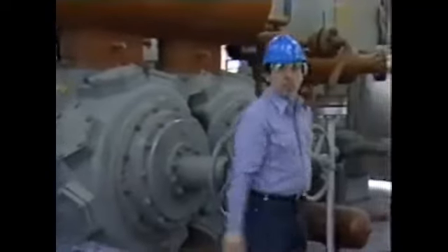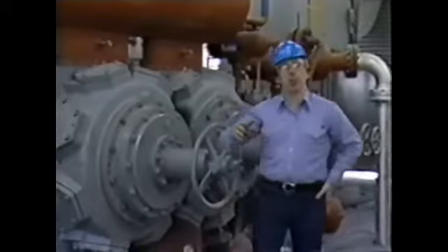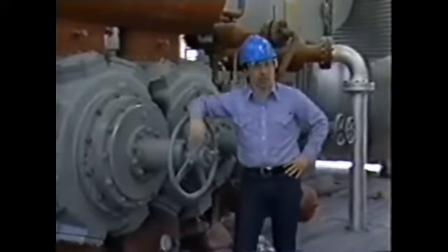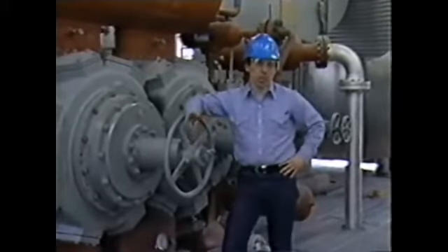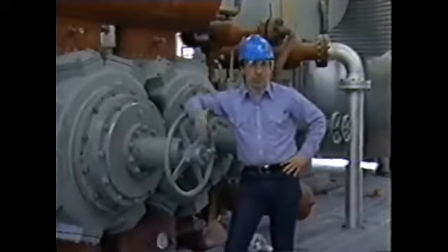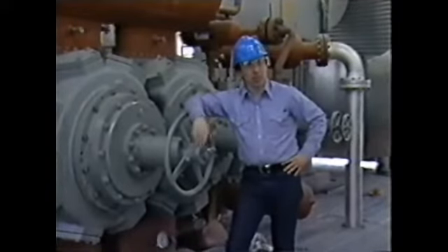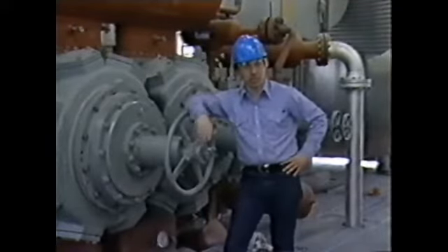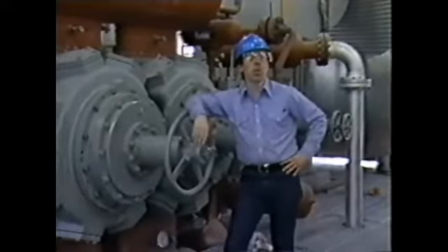In certain instances, gas must be compressed from a low pressure to a high pressure to meet sales requirements or field applications. This increased pressure is accomplished through stages of compression. But due to the amount of power required, it's not feasible to raise the pressure of the gas from low pressure to high pressure in just one step. Because of this, we use what's called multistaging.